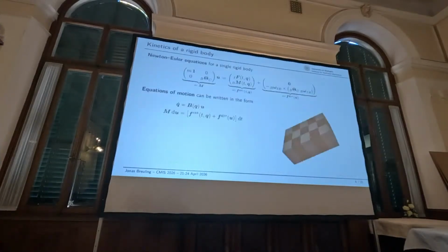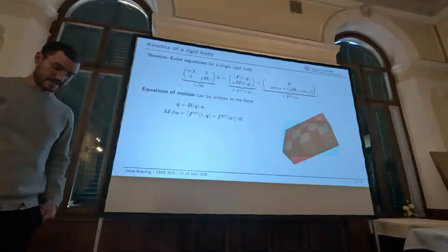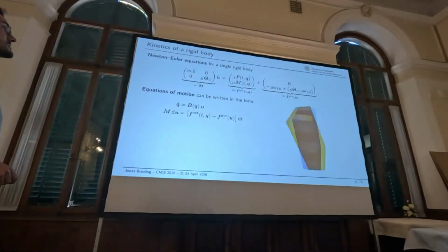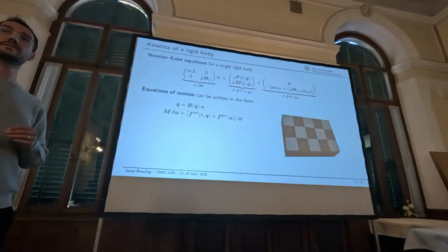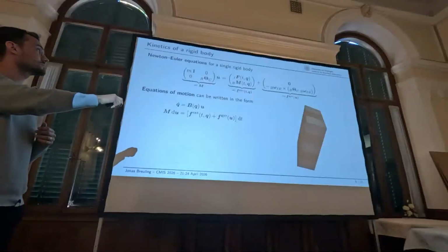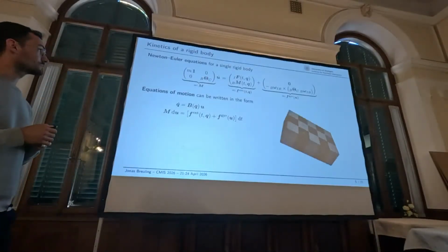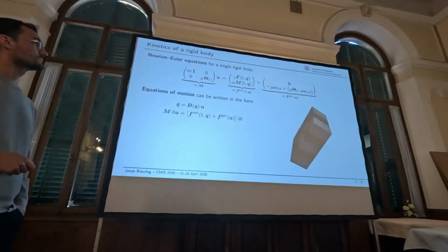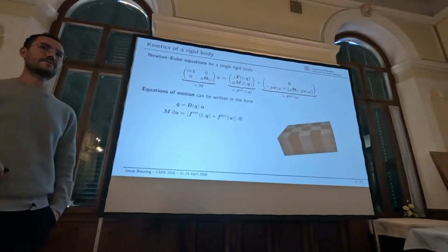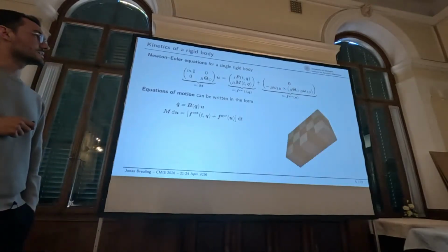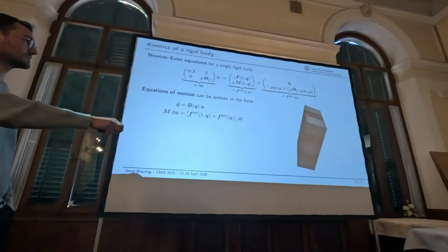And if we go on to kinetics, we can simply use the Newton-Euler equations, or we can derive them. It doesn't matter. In the end, we have this set of equations, which is very simple. So we have a diagonal part for the translational velocities or accelerations, and typically also a diagonal part for the inertia, if we choose the right basis for this tensor here. We have external forces and moments, and one point which is not that nice is that we have a bilinear, skew-symmetric gyroscopic term here, which is troublesome in highly dynamical systems.